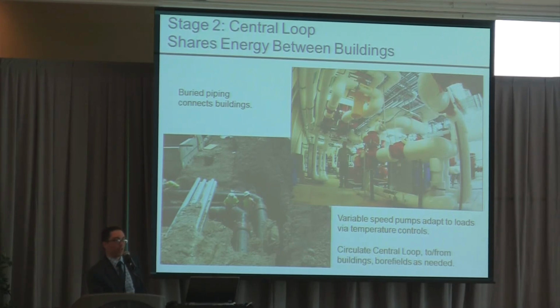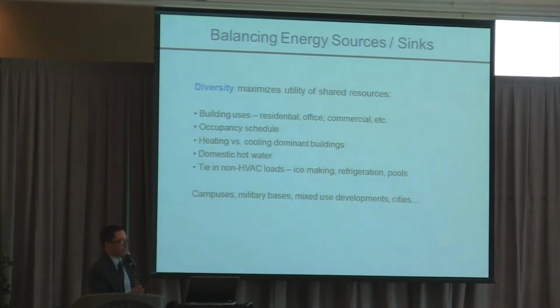You'll find that with diversity across the campus, many times you have certain buildings that are cooling dominant and other buildings are heating dominant. So in general, your commercial spaces are going to be cooling dominant because of higher occupancy, probably higher solar gains, etc. Residential areas are likely to be heating dominant, at least in our climate. And so by connecting these buildings, you expand that ability to take advantage of system diversity and recover energy on a building by building basis, the same way that many systems in place already do, zone by zone.